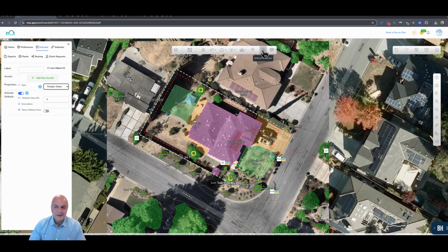That's a possibility, but obviously you will know. So electric line goes from here to here. And basically I'll add that in as being the electric line. So, it puts it in red and marks it as electric line. So basically with this advanced process, we can define every piece of the property site plan.